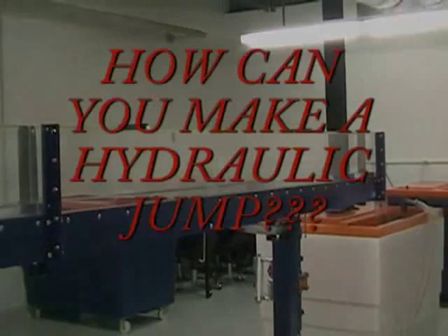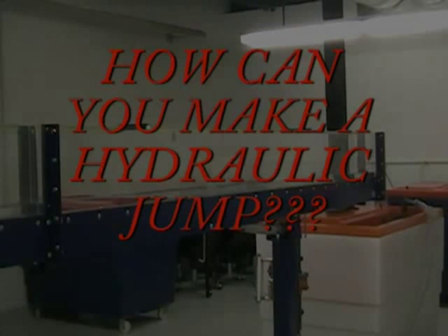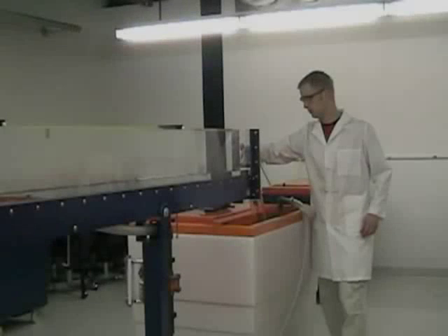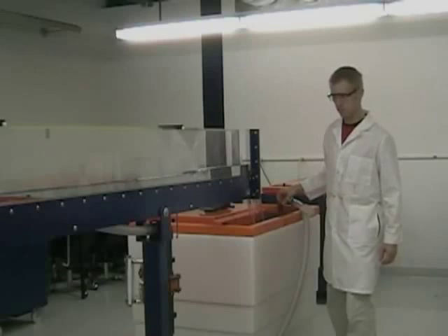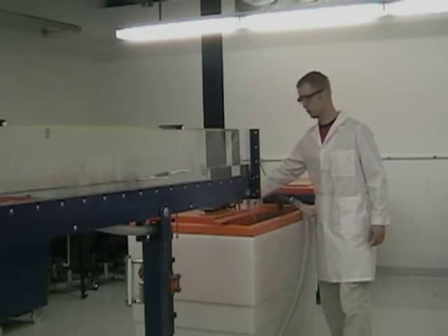In this case, we see that the flow of water in the flume is at or near critical depth. Take a moment now and think of ways the hydraulic jump could be created in this condition. Since the flow is near critical depth, we can use the stop logs at the end of the flume to create subcritical flow.